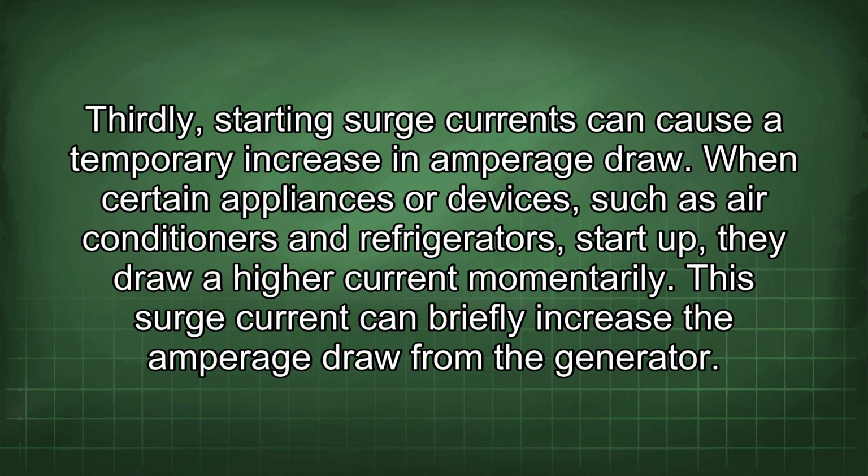Thirdly, starting surge currents can cause a temporary increase in amperage draw. When certain appliances or devices, such as air conditioners and refrigerators, start up, they draw a higher current momentarily. This surge current can briefly increase the amperage draw from the generator.